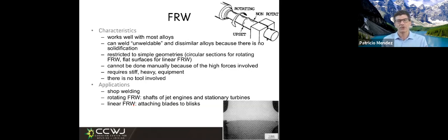Circular sections for friction welding and flat surfaces for linear friction welding. It cannot be done manually, same as usual, because the forces are too high. Stiff, heavy equipment. In this case, there is no tool. The applications are shop welding and things, and much of this is aerospace. An interesting thing,